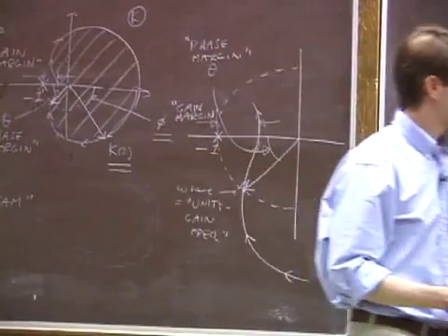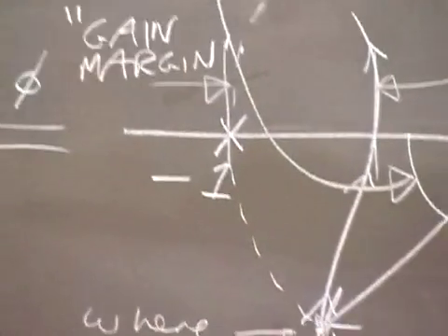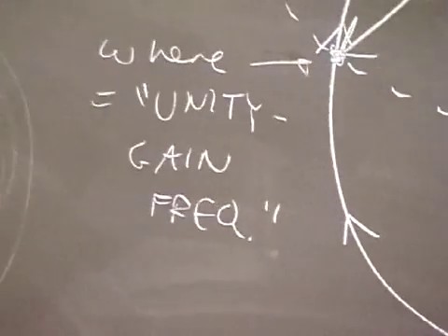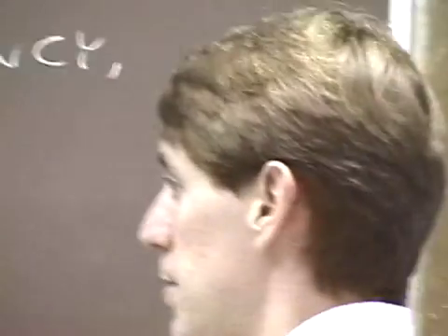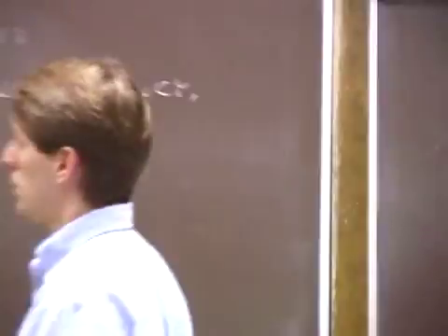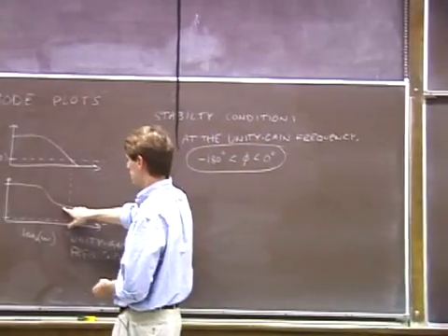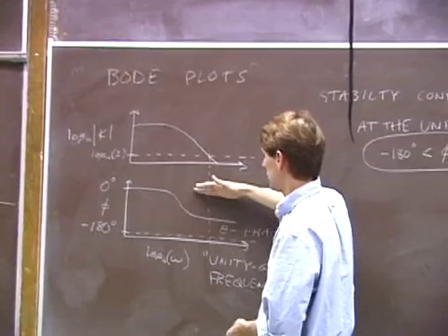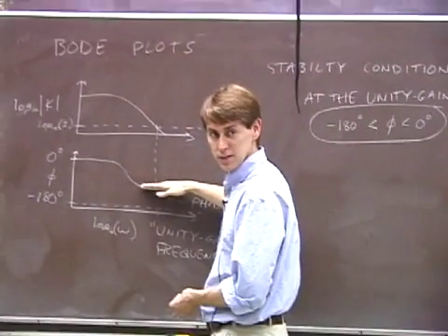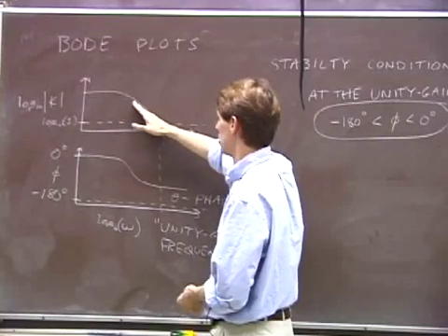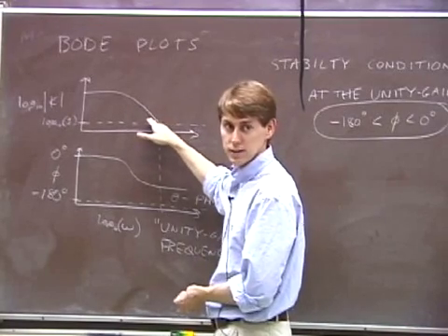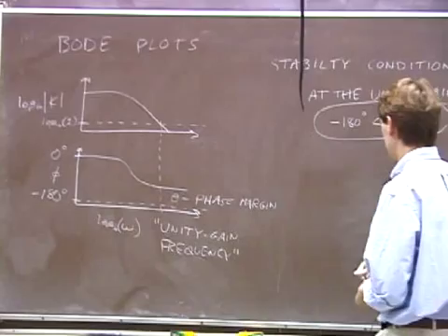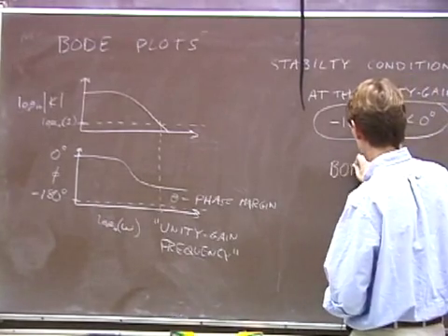So, now I'd like to point out one thing. There's a theorem, and it's related to the Kramers-Kronig relations. If any of you are familiar with the Kramers-Kronig relations, you may be able to see the connection. But there's a theorem that relates the phase of a transfer function, or I should say the maximum phase of any transfer function, to the behavior or its scaling in its magnitude. And these are Bode's gain phase relations.